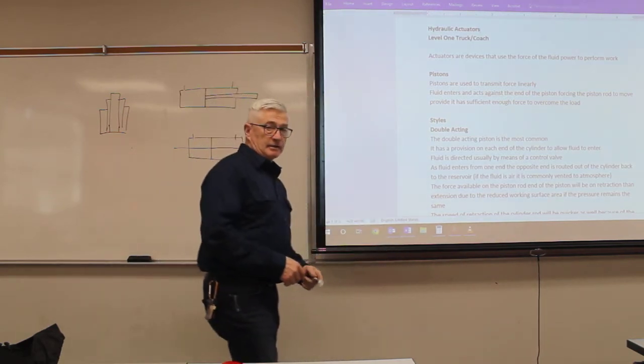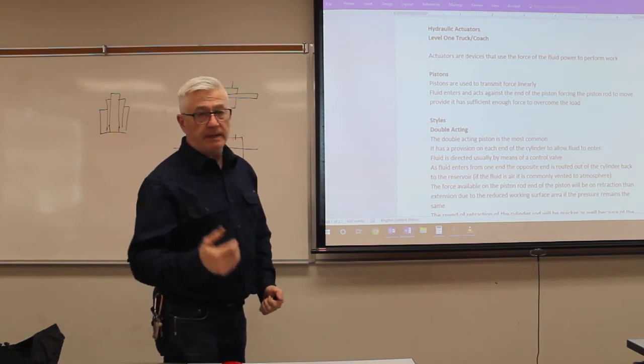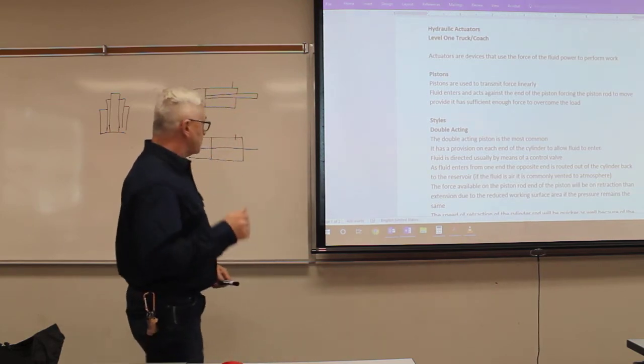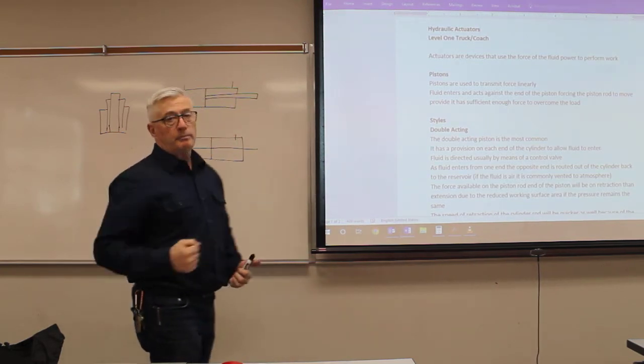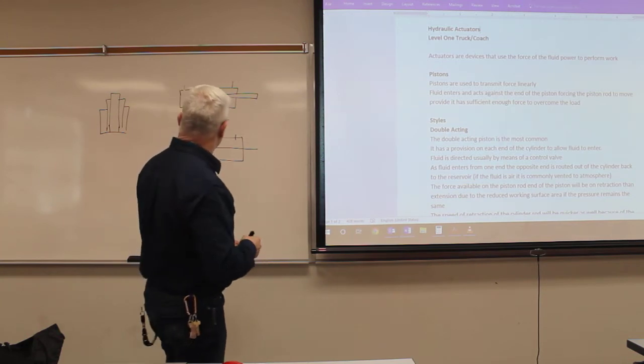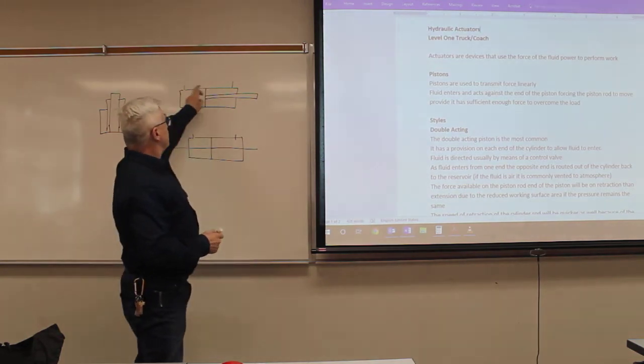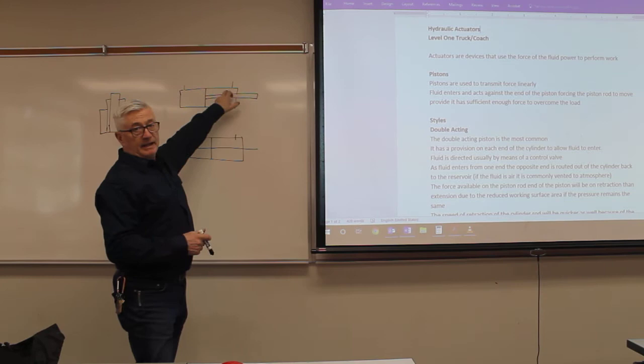Styles, double acting. So a lot of our implements are used double acting because we want to not only just push it out, but be able to power it back on retraction as well. Simply means that we have a fluid outlet at each end.